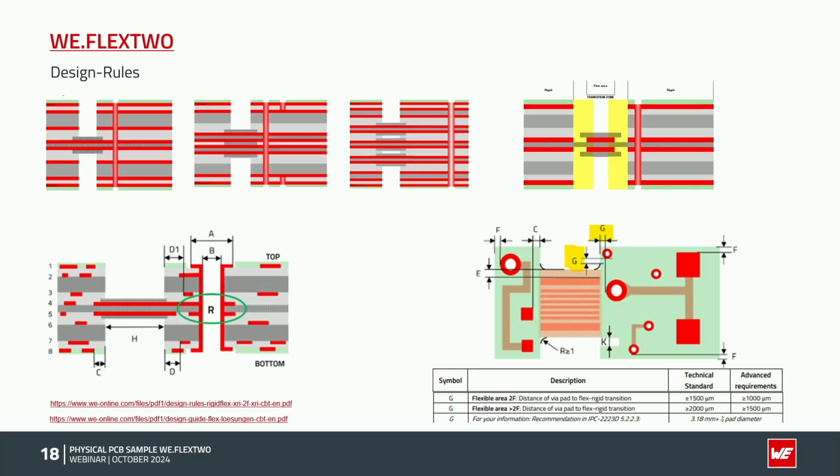And we have a lot of questions and discussion with customers why we need this distance and why they have to shift drillings. This is just because of technical restrictions, yeah, and IPC standards, which need a minimum overlap, and that's what we have, of course, in our PCB and in our manufacturing as well. We define here an overlap of the cover layer, and this is defined 0.6 millimeter minimum, yeah, and that's the reason for the values we define here in our design rules.